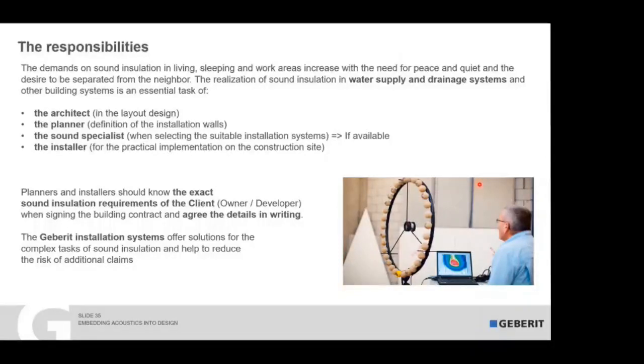Then also the planner, of course, with the definition of the installation walls. Do we go with solid walls? Do they choose dry walls, which are of course also better for acoustic installation? On some projects, we have even sound specialists, so they consider the full building aspect, not only the pipes. Depending a bit on the region, we see more and more sound specialists involved, depending also on the size of the project. And then, of course, the installer for the practical implementation on the construction side. If everything was done well before, and he does a good installation, then and only then we can make sure we can meet the requirements of whatever regulation we aim for.